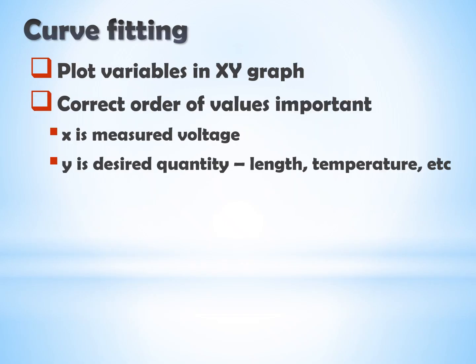Curve fitting. Let's look at the first method. It starts with plotting the data on a graph, in which the x-axis represents the measured voltage, while the y-axis represents the desired output, that is, length, temperature, pressure, and so on.